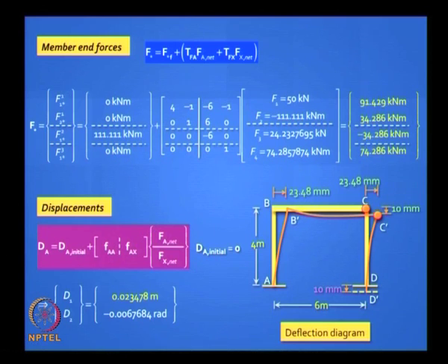Now you get the same sway at both ends, but it is very close to what we got earlier, and the deflection at C earlier was 10.07 mm, now it will go down only as much as the support D goes down. Is it clear? So we have tackled this problem in many different ways, we are very clear what is going on.